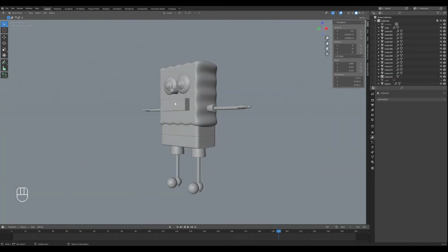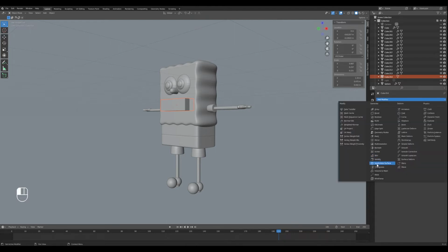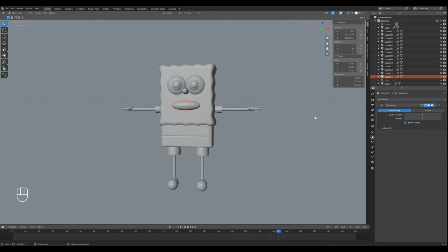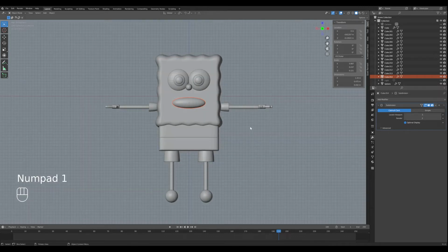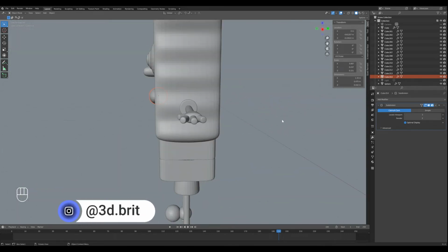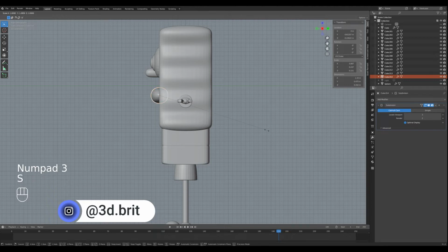Okay, you're kind of like, what are we doing, right? So let's click this. We're going to add the subdivision surface modifier. And I'll show you. Click the levels of viewport up to 3. That's my preferred. Usually I kick it up to 3. Okay. Let's see. We're going to scale it along the Z like this here.